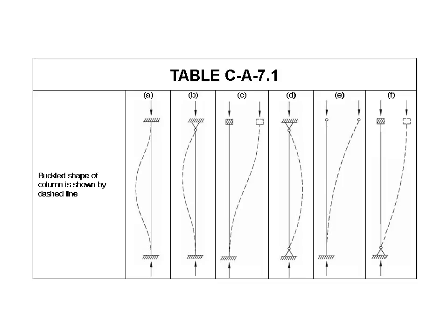Here is the table of theoretical cases for K, for columns based on their idealized end conditions. It's very familiar. We have two cases with end conditions that prevent rotation and force a curvature that's shorter than the actual length. That's illustrated on this slide in red. We say KL is less than L, so K is less than 1. The next two cases both have a buckling length that equals the actual length. KL equals L, so K is 1.